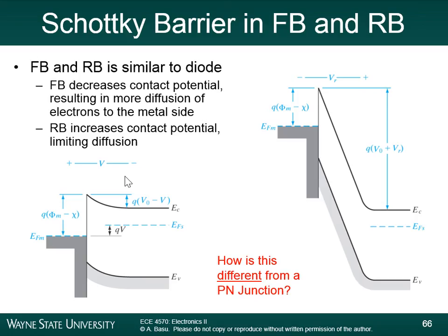Holes. Yeah, exactly. In this N-type Schottky barrier, we have a metal and an N-type semiconductor junction. The electrons are pretty much doing everything here. The electrons are responsible for electricity going through the Schottky barrier. So there's no holes involved. That's one of the big differences.